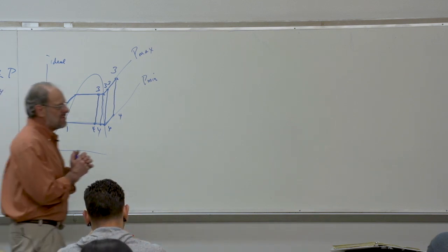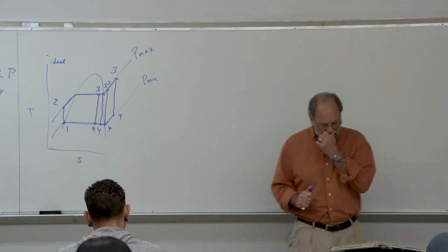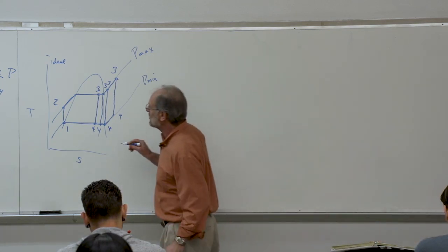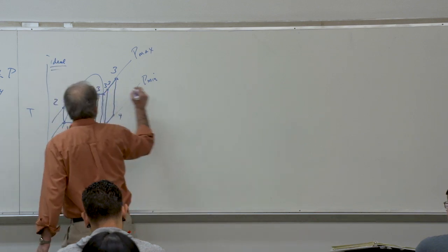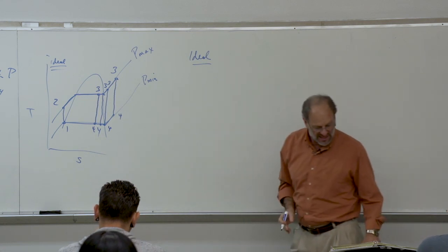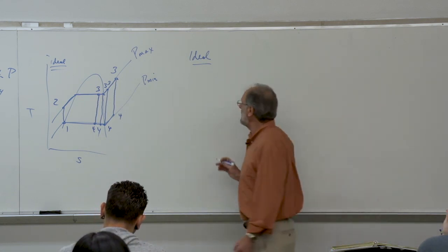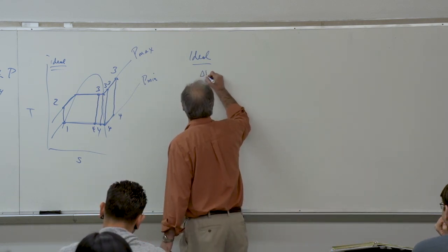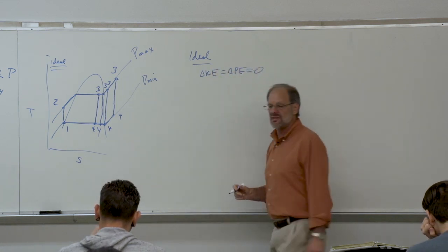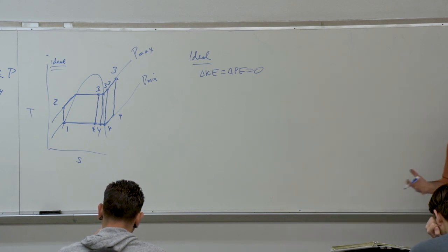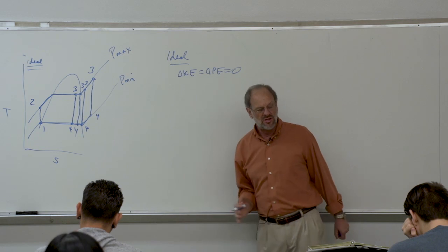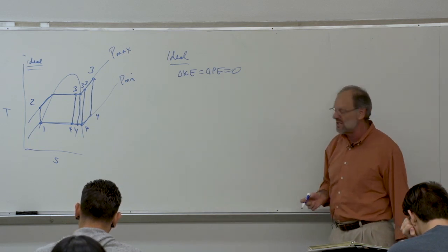Anyway, let's start looking now at the equations that would be appropriate for this type of analysis. Again, we're specifically looking at the ideal case, and still the simple Rankine cycle. In this particular case, let's note again that for all situations, we're assuming there's no change in kinetic or potential energy, as usual, right? There's no significant velocity or velocity changes through any of these devices. There's no significant height changes, so those are going to be neglected.